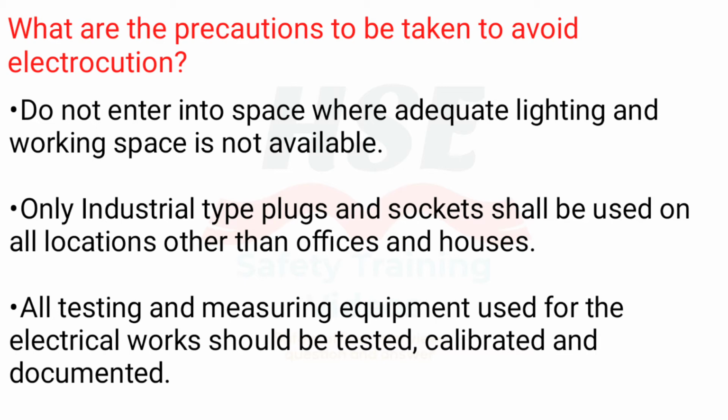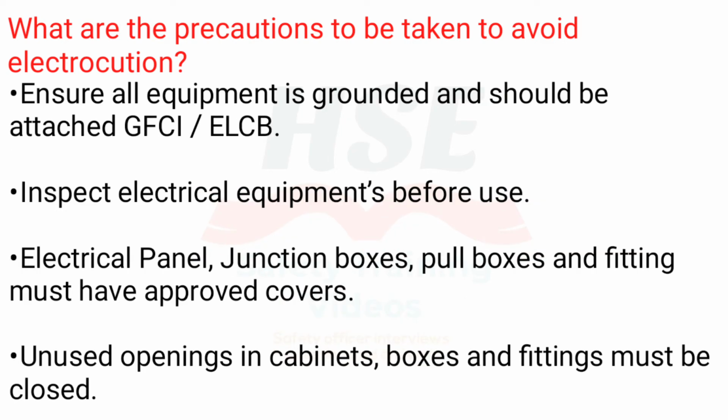Do not enter into space where adequate lighting and working space is not available. Only industrial-type plugs and sockets shall be used on all locations other than offices and houses. All testing and measuring equipment used for the electrical works should be tested, calibrated and documented. Ensure all equipment is grounded and should be attached to GFCI/ELCB. Inspect electrical equipment before use.